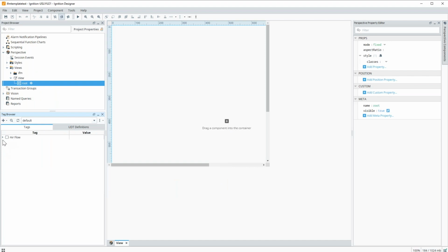Now you have an airflow sensor, and you have all these specific UDTs, and you see the data coming in. So in this case, we're getting the flow data from this particular device. We're getting pressure information from the device, temperature, and we're also getting a totalizer count here. You know, just having to use these is fantastic. This is such an easy way for us to get the information in the relative context that we're looking for, right? As you see, there's no scaling. All that stuff is done. With IO-Link, you're actually getting the true digital process value of the sensor.